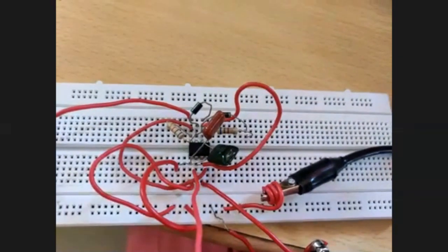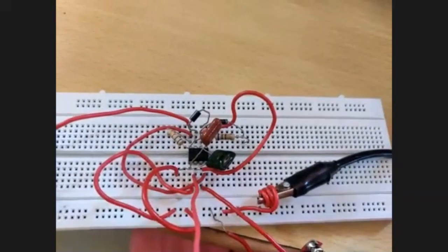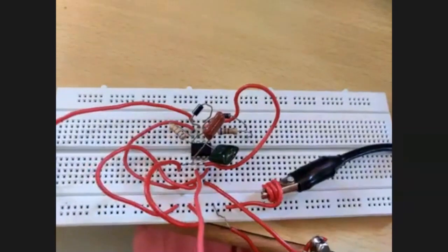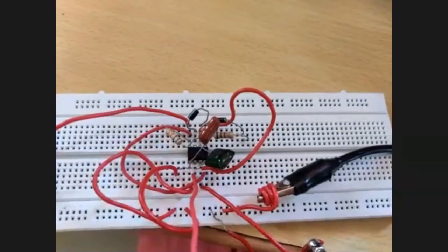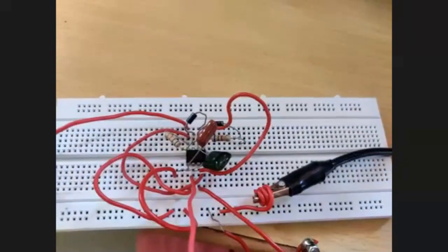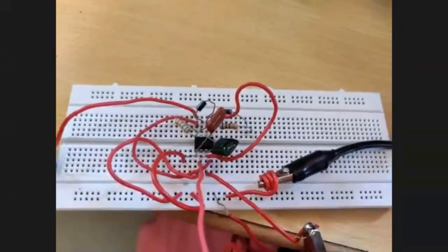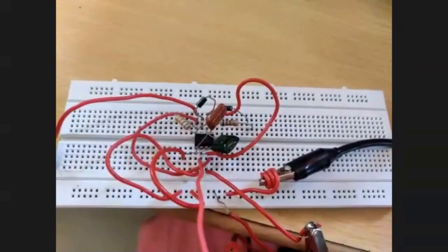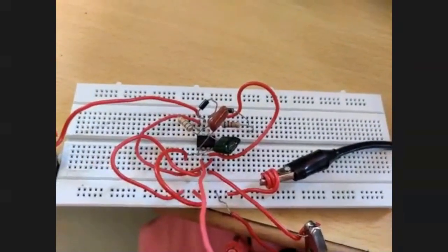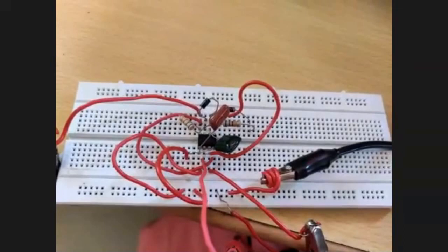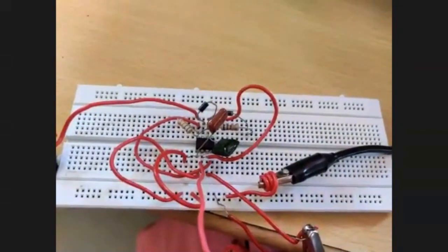So next is the symmetric astable multivibrator. In the symmetric astable multivibrator, I already told both T on and T off are equal, that is 0.5 millisecond, 0.5 millisecond. In the astable multivibrator, we are not using any triggering because it is changing between two states. It doesn't have any stable state.